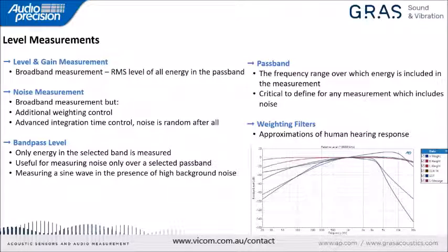And you'll see this very commonly when, for example, people will describe the noise level in a building. They might say, oh, in this building, the noise is 60 dBSPL A weighted. So in that case, they literally mean they made an amplitude measurement in that environment. That's dBSPL.